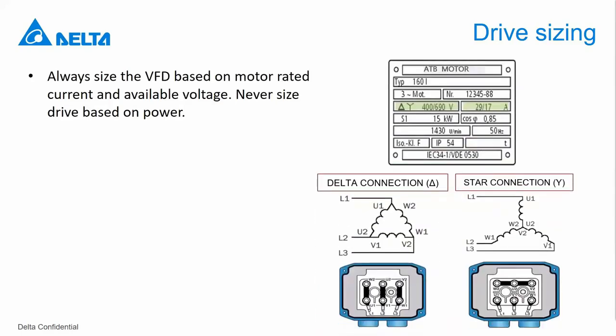So next, I am going to talk a bit about how to size a drive. So which drive is right for which application. The first question you should ask is which voltage is available? Do you have 400, 200 volt single phase, 200 volt three phase? Most commonly, you will have 400 volt three phase, or sometimes depending on your location, you might also see 690